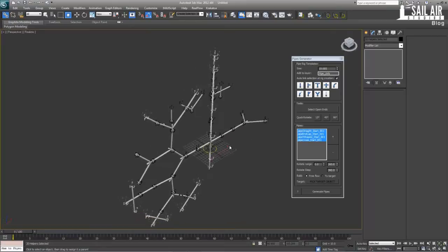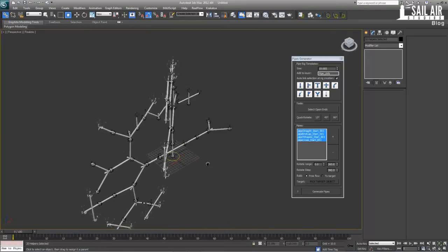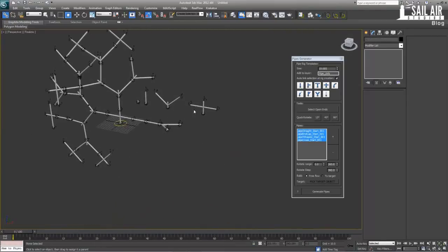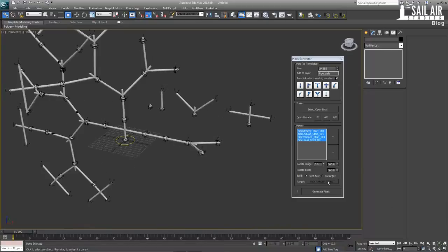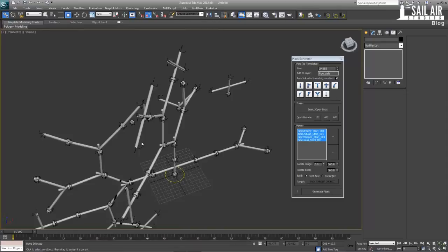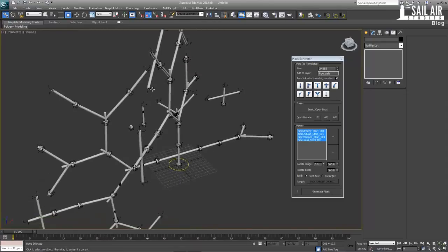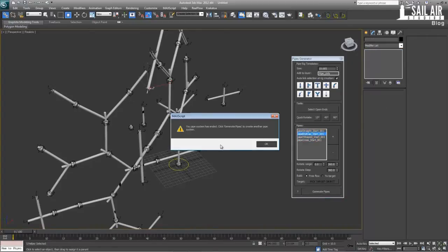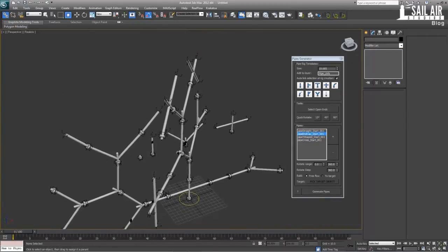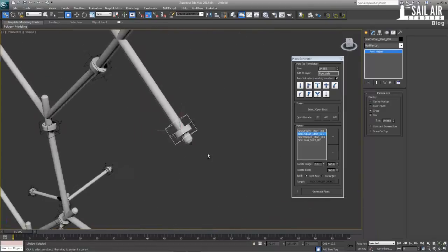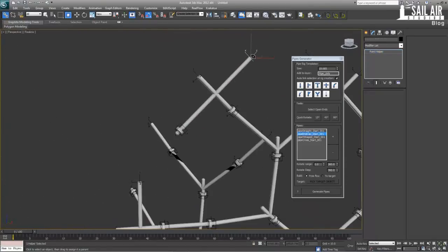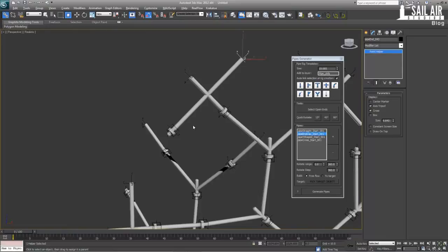Here, let's quickly go over the tools in here. Let's say you click away from here, right? And as I said before, it generates pipes from wherever you were last touching it, I guess. So it generates pipes from where you're selected. So if I want to generate pipes from this one, I would select this, hit the end cap one, generate pipes, and I ended that system, as you can tell. See, there's no more caps in it. But it generated from there.